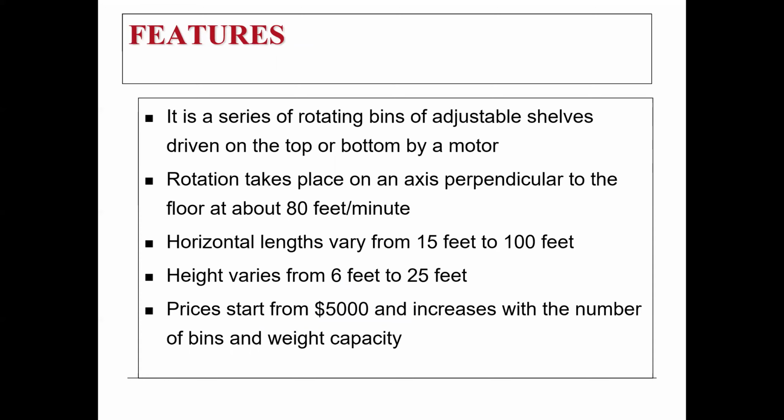Features: it is a series of rotating beams of adjustable shelves driven on top or bottom by a motor. Rotating takes place on an axis perpendicular to the floor at about 80 feet a minute. Horizontal lengths vary from 15 feet to 100 feet. Height varies from 6 feet to 25 feet. And prices start from $5,000 and increase with the number of beams and weight capacity.